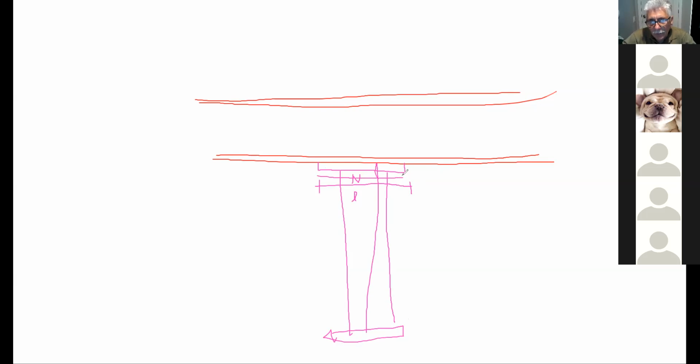Okay, that makes things a lot clearer. Thank you, sir. For example, I'm pretty sure that if you didn't have a cap plate and you just took the size of your column, most likely it would work. But the real value is the length of this bearing. In other words, from here to here is where the web would start crippling. So that's why you take this as the value. It allows more of that force to be distributed over a bigger area, less of a chance for it to cripple. And that's what the N value is, the length of bearing.